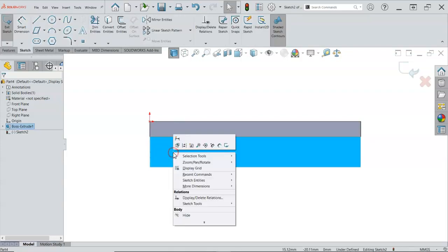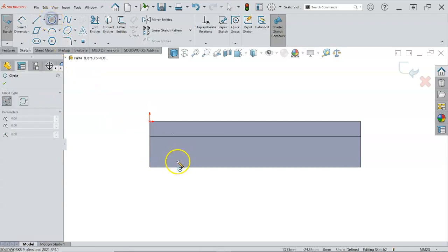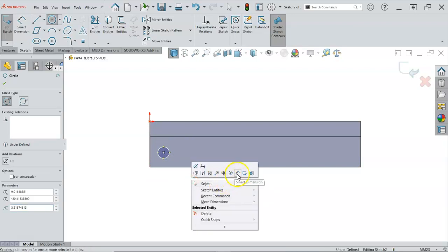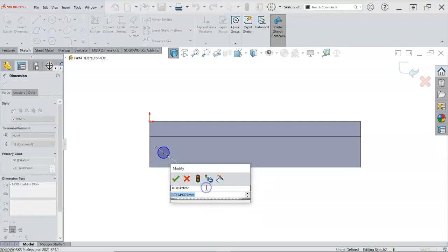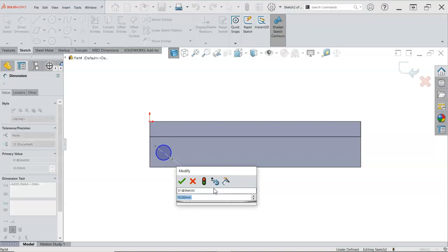All right, so right-clicking on the face, going into that sketch gets us started. And pick the circle, and click, and if it still continues to drag, I'll click again. Going to put a dimension in for our diameter. Well, another missing dimension, so we will go with the 10. That looks a little bit big, so maybe 8.